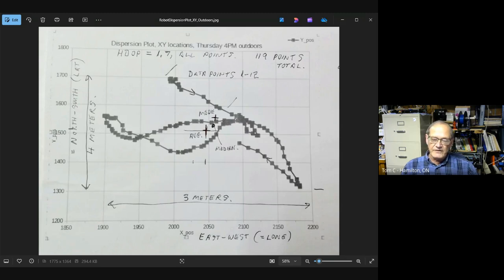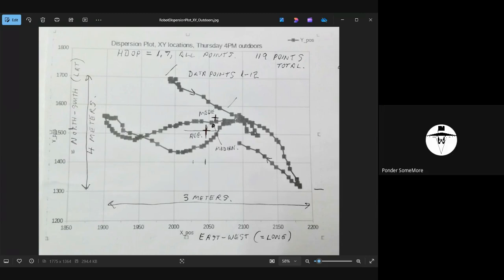One of the things that I discovered in my research is, of course, that this system is using the L1 C/A GPS signals. The L2C signals are available, but you need a significantly different receiver in order to accept them. And if you can receive them together with L1, you can apparently get more precision in GPS measurements, although I could not find any statement about how much better. So my first question is, are any of you using a GPS receiver that's L2 capable? And have you noticed any improvement in accuracy? Everyone who's using the F9P has L1 and L2.